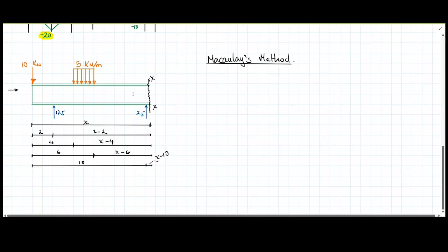during that time. So Macaulay considers that once a term of the Macaulay's equation is on, it remains on all the time. Meaning that when I come to the distributed force, when the distributed force is on, it won't turn off until the end. So it would just continue to turn on. This means that for Macaulay's, once you reach this length at x equal 4, this distributed force is going to be acting all the time.